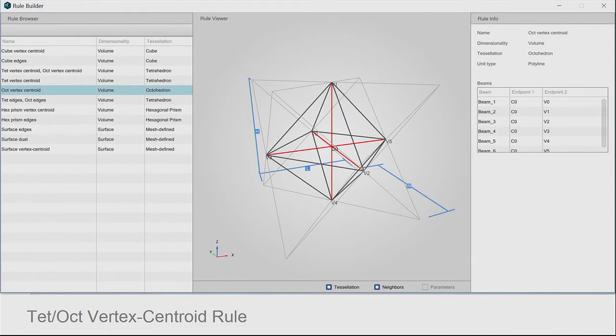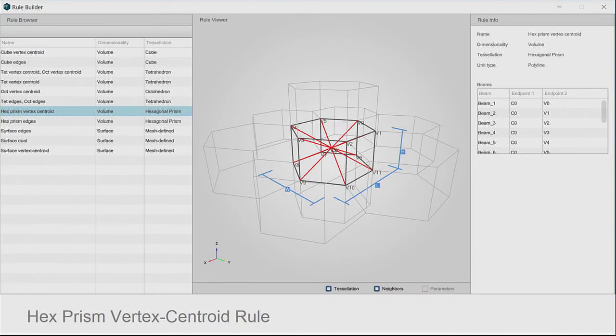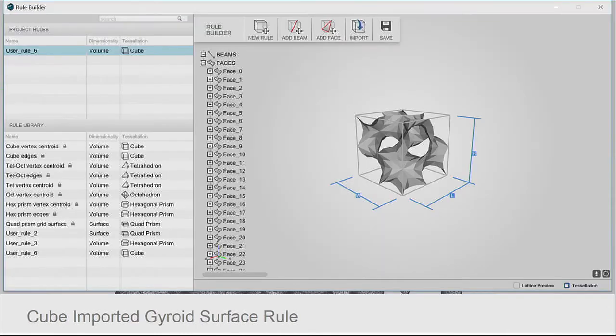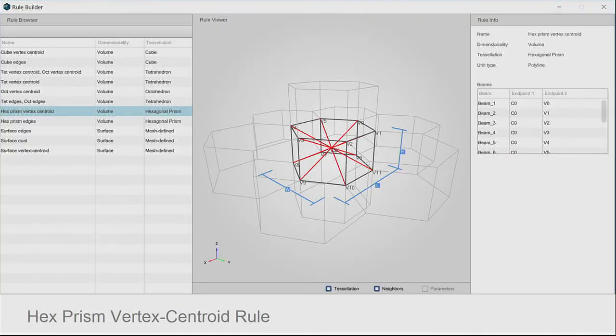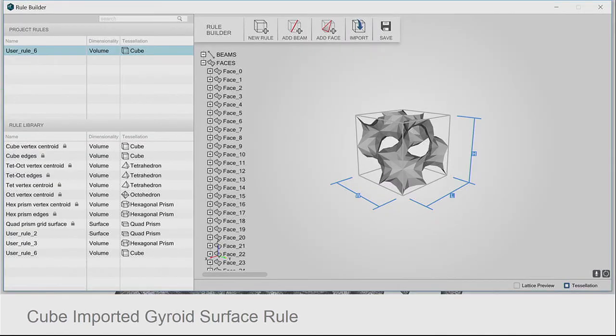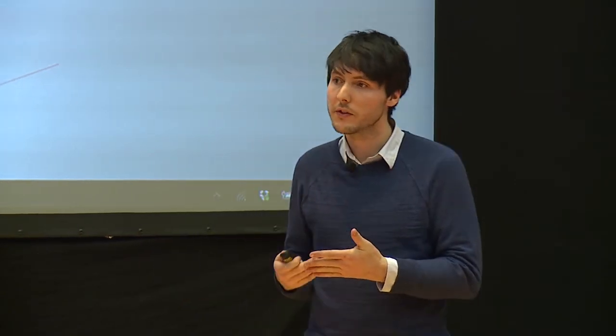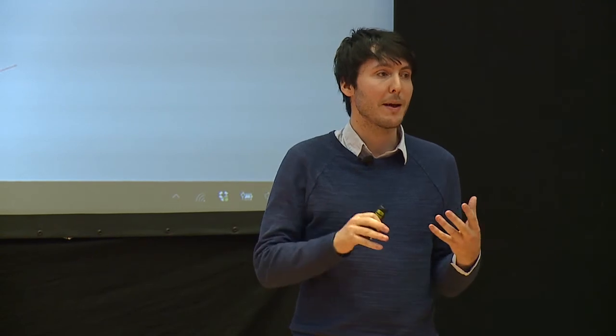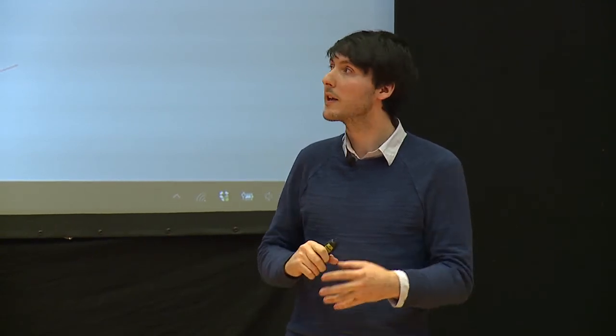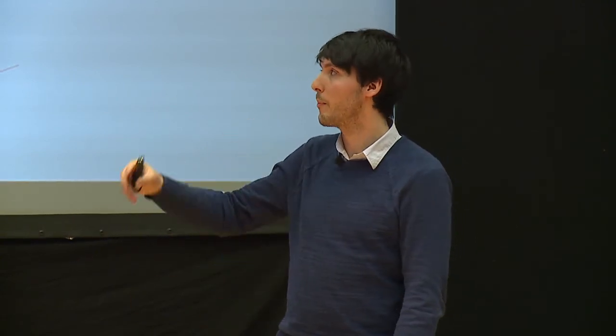And that unit cell type can also vary. And so we have a couple different rules. These rules are based on beams, so node and beam-based structures. We also can represent surface-based structures or faceted structures as well. And so the normal workflow through Element when we're generating these parts is you're going to start with a part, or you're going to import your part, right? You probably have an assembly in SolidWorks or in NX, CATIA, you'll export a part from that assembly and import that into Element.